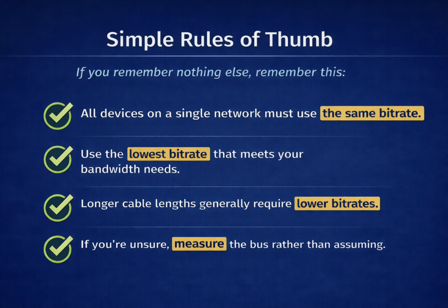If you remember nothing else, remember this: all devices on the same network must use the same bit rate. Use the lowest bit rate that meets your bandwidth needs. Longer cable lengths generally require lower bit rates. If you're unsure, measure the bus rather than assuming.